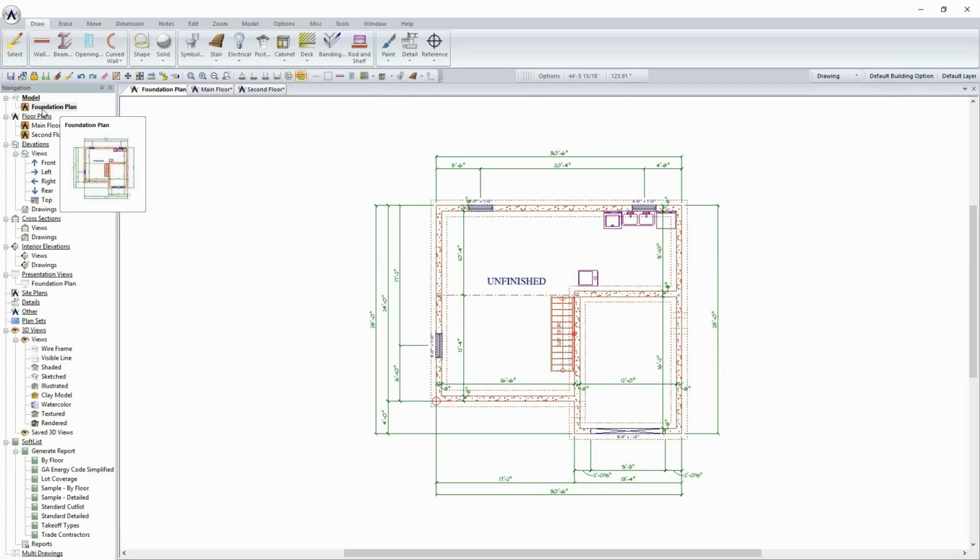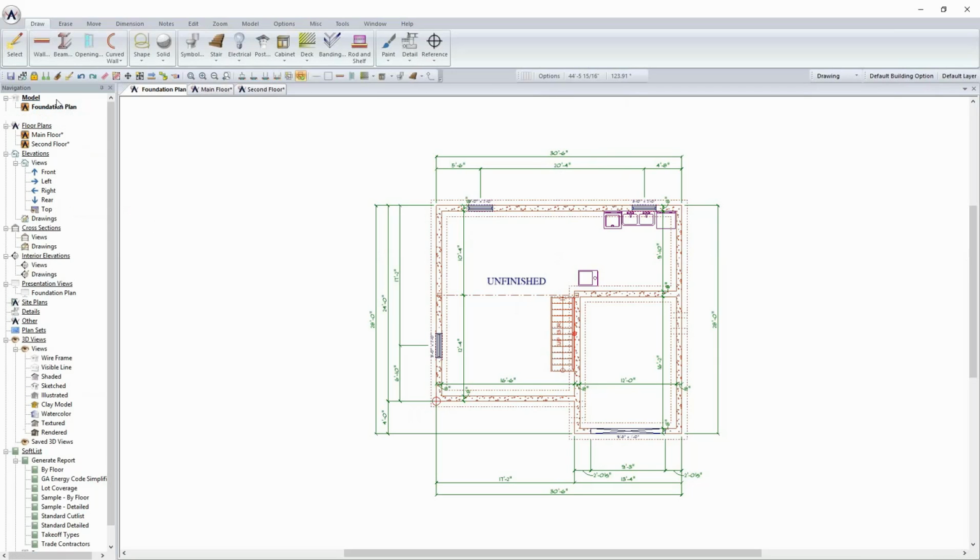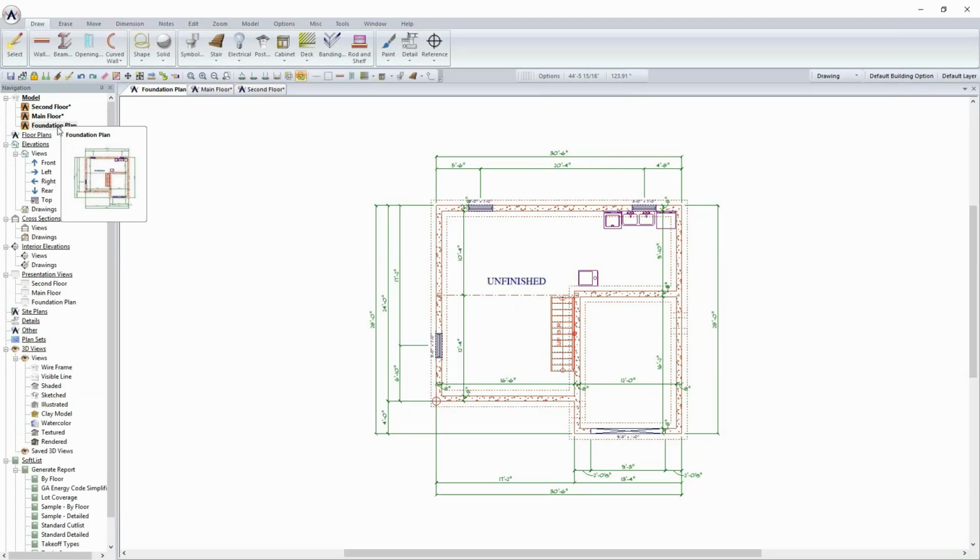So as I drag these in, I will drag them in the order that I want them to be calculated, in particular if I'm doing it on a per floor basis, okay, so that they are listed out. Once these are stacked in the model, I will then be able to go ahead and calculate the complete bill of materials according to different configurations called material definitions.